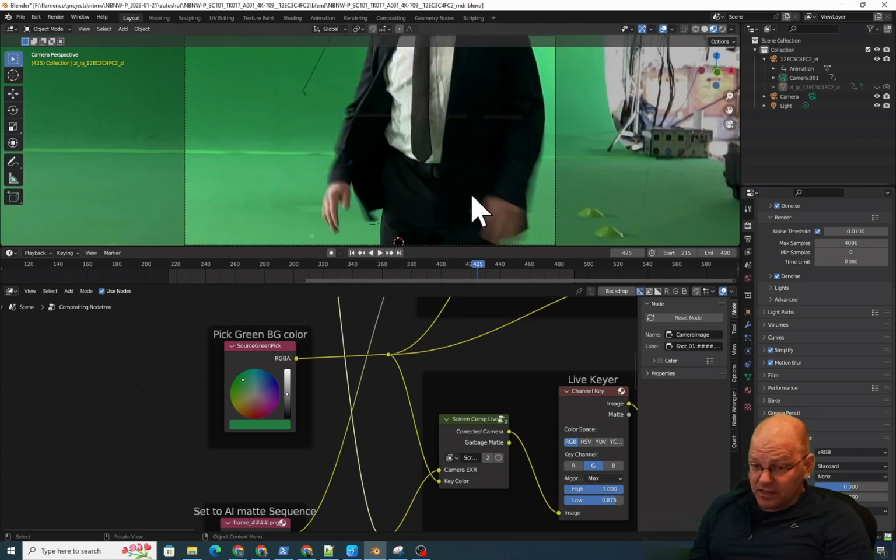Now, note that this means that we will need to use a node in the compositing tree instead to use things like Blender Filmic to get the 3D rendering to look photographic. You'll want to look at the settings of your original scene file, then transfer those settings to the correct node in the compositor. We'll get into that in a later tutorial.